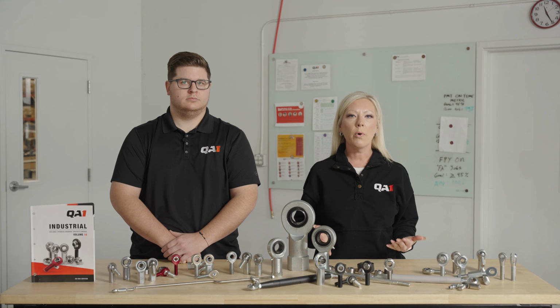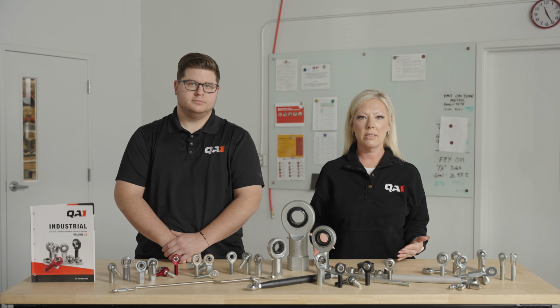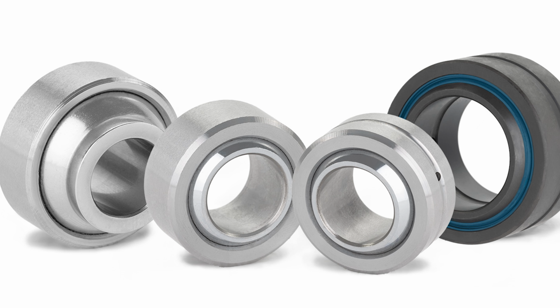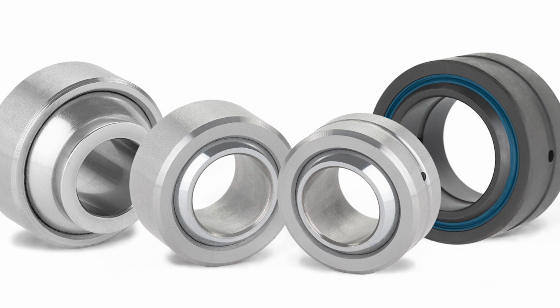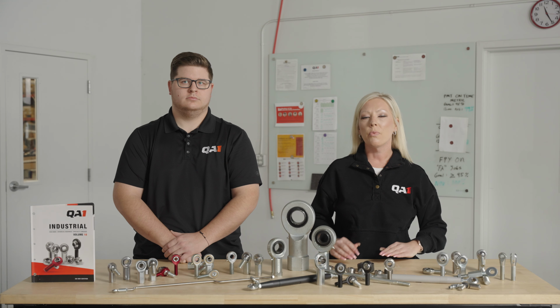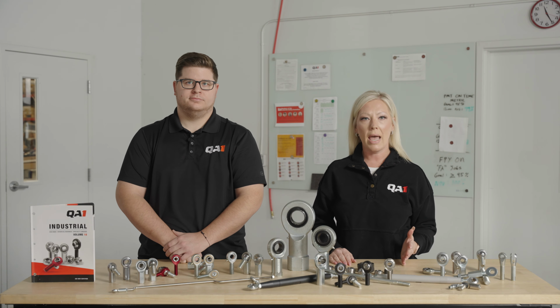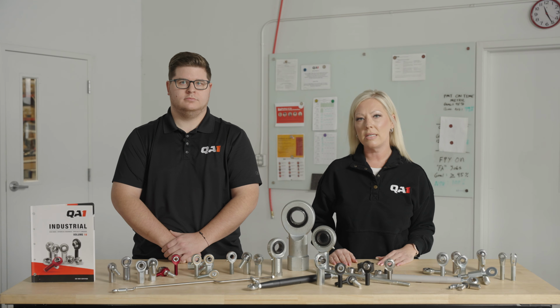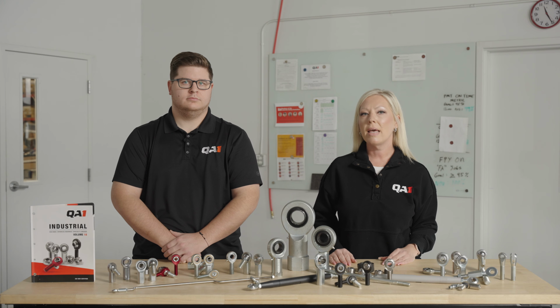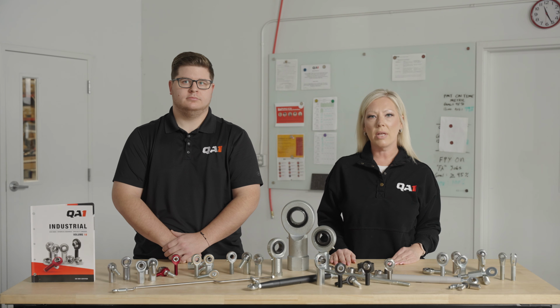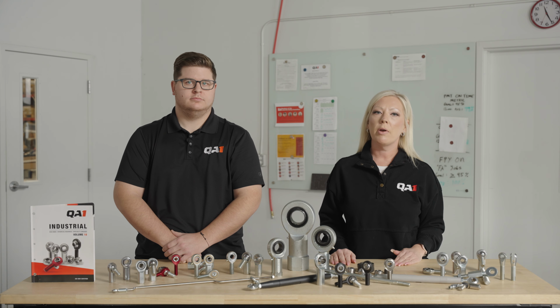So we offer 4 basic types of spherical bearings: fractured race, commercial, precision, and unique dimension variations. The range of options also include alloy, carbon, bearing steel, or stainless steel. They come in metric and inch sizes, high misalignment variations, narrow and wide options, self-lubricating liners, and sealed options like our GEZ series. Also, most of our bearings are protective coated for corrosion resistance.